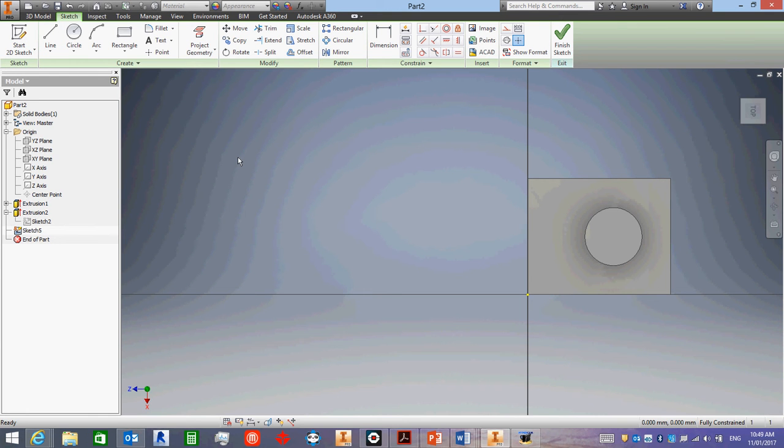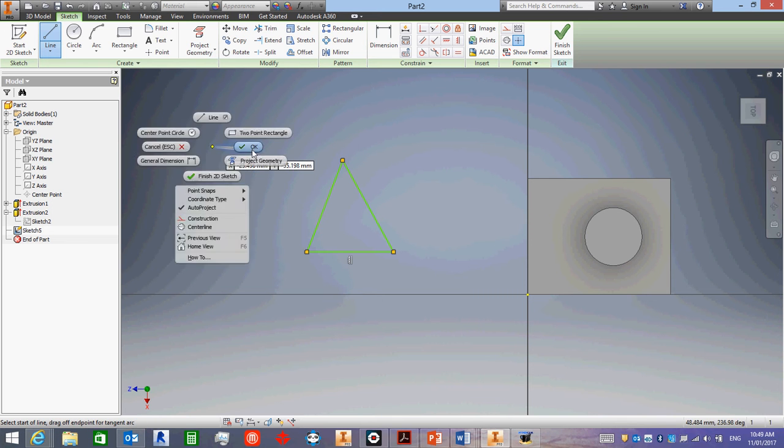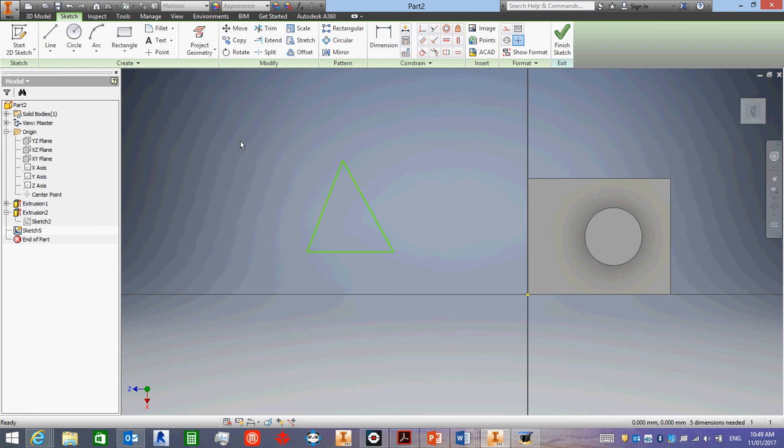So what does a cone look like? Well, a cone is a triangle, so I'm going to draw a triangle. But this is wrong. I've drawn it wrong, because what the Revolve does is that you only take half of the shape. Because the Revolve is like two shapes beside each other. When you cut it in half, you see two identical shapes beside each other, and then a line down the middle that the shape spins around.